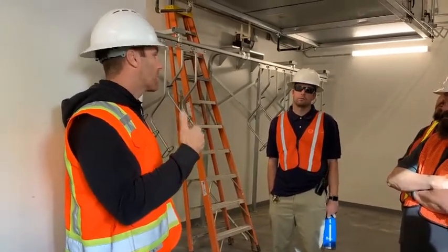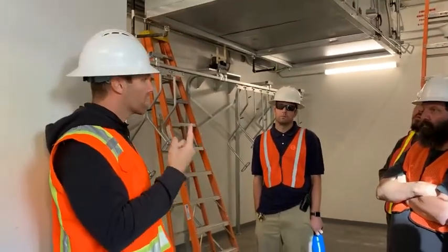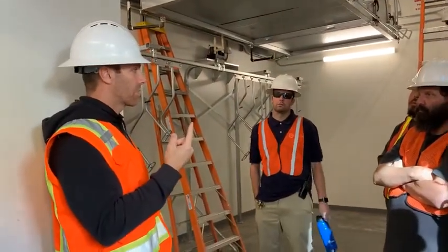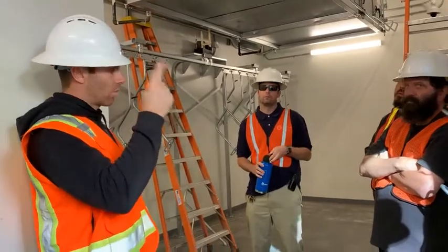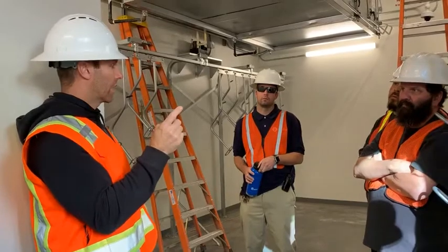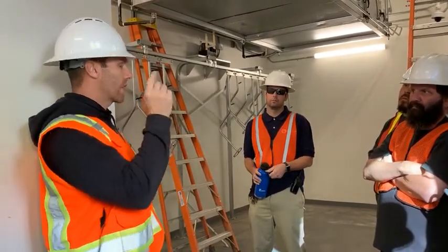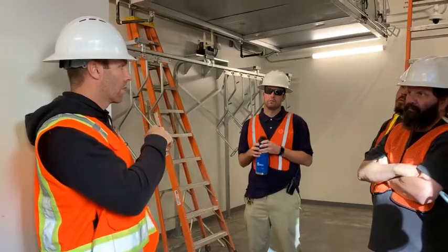First thing you need to do is open the fixture. How many drivers do you have in there? Most of the time you're going to have one driver in a fixture. That one driver is going to have low voltage coming out to the LED board, powering the whole LED board. If that's the case, and all those wires are connected, most likely a partial LED board is out.